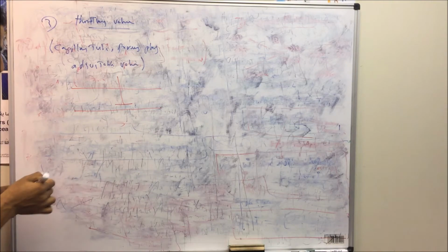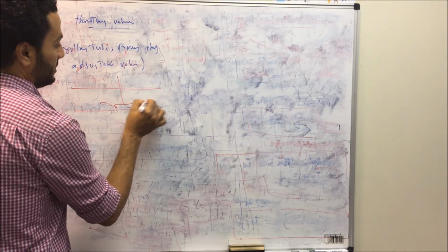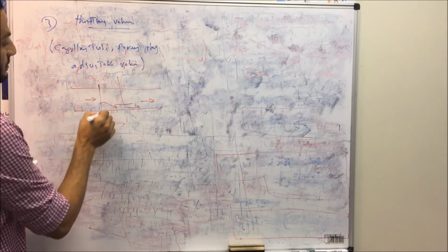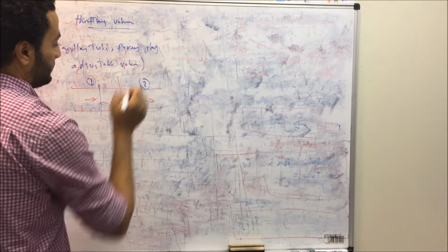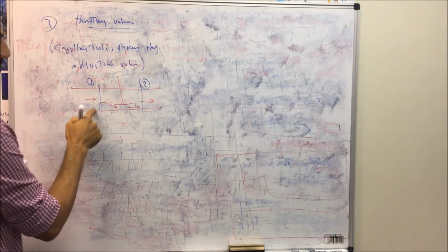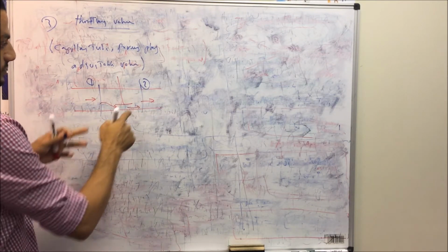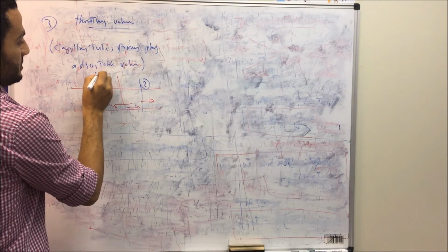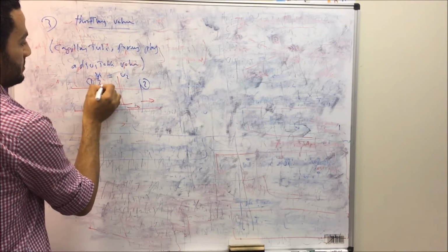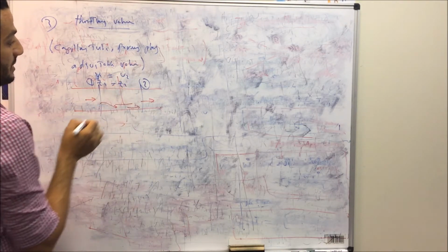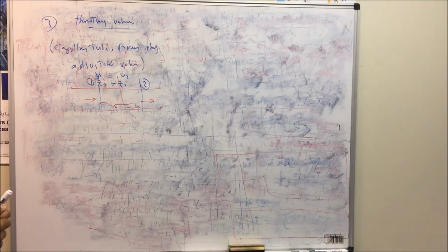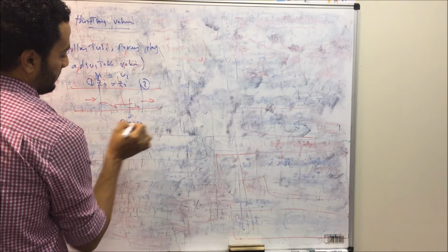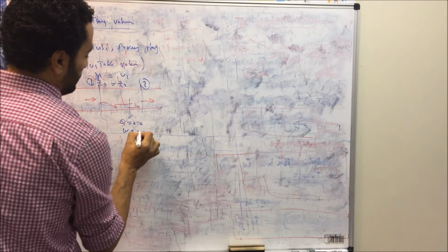So this is the valve, and the flow is forced to go through a very small area. Let's say this is cross section number 1 before the valve, and this is cross section number 2. Between cross sections 1 and 2, we have the same cross section area after the tube, so the flow will build up again and attain the same velocity. So velocity V1 is the same as velocity V2, and the elevation Z1 is the same as the elevation at the outlet section Z2. Usually through this valve we don't have any heat losses, and also we don't have work.